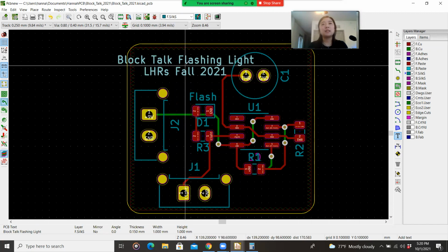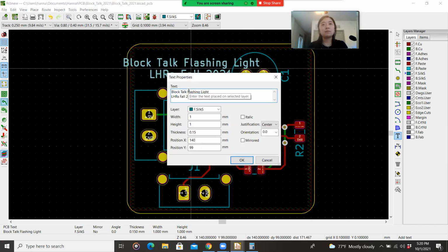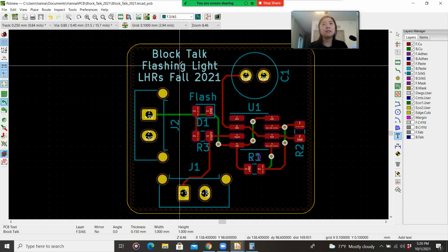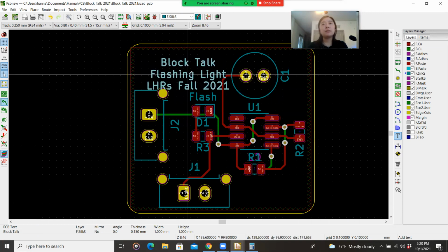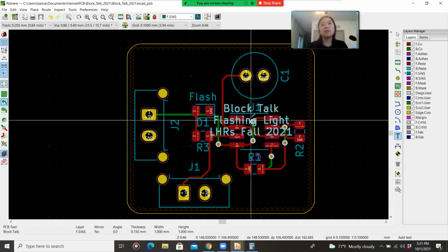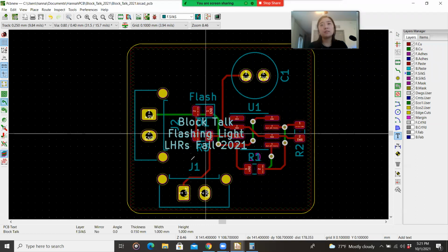Notice that this is kind of too big. So what happens if we move it to the next line? Okay, and we can fit it here. It is okay for the text to cover over the copper trace, but we don't want it here or anywhere like here, because then an actual part is going to be placed there.